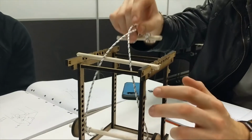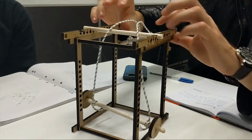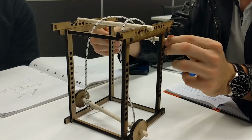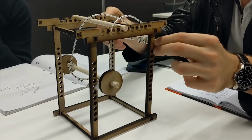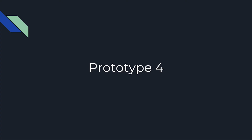Advantages of this design are a lightweight and simple design when compared to the other prototypes. Its design allows it not to impede the athlete's movement or force any changes to exercises, and it also allows for unrestricted movement in all directions. Disadvantages are, it requires slight modification to allow for 2 independent motors to raise the bar separately, and it is unable to restrain the bar in all directions when the safety mechanism activates, only stopping its vertical movement.